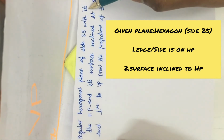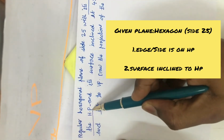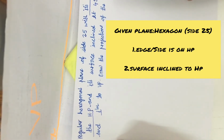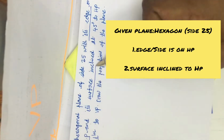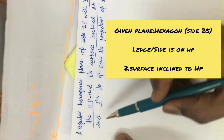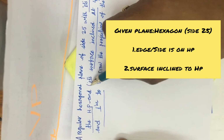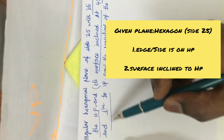What is on the HP, dear students? Its edge, I mean one of its sides, is on the HP, and its surface is inclined at 45 to HP. What is inclined, dear students? The surface is inclined at an angle of 45 degrees to HP. Please do concentrate on this part. And perpendicular to VP. So its surface is inclined at 45 to HP and perpendicular